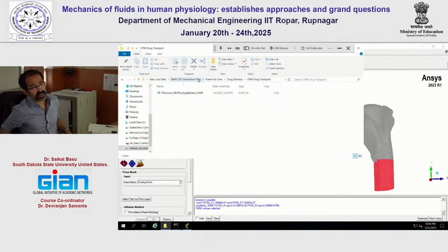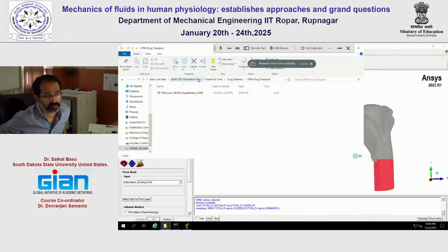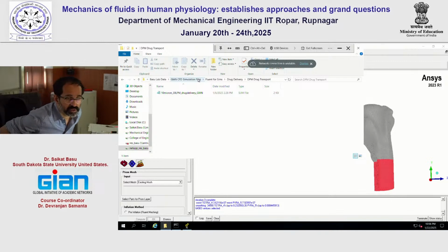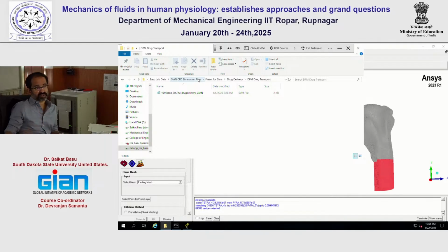If you don't do anything, it would by default assume a spherical shape. But if you want to control the shape factor, you can do that using user-defined functions in Fluent. Now you can figure out what the shape factor could be for whatever shape we are trying to track. But then again, there is this limitation: that shape would get fixed. It would not deform because that is not supported under inert particle tracking. It is a rigid particle with just a different shape factor, basically.